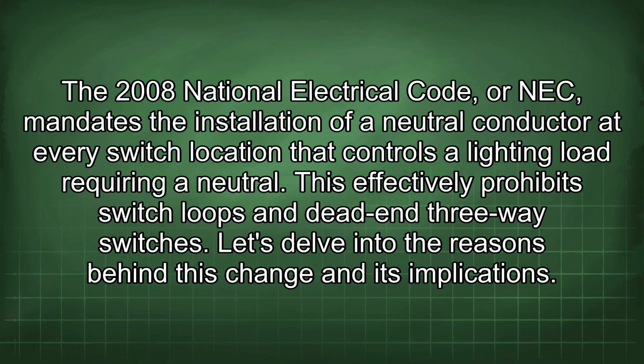The 2008 National Electrical Code, or NEC, mandates the installation of a neutral conductor at every switch location that controls a lighting load requiring a neutral. This effectively prohibits switch loops and dead-end three-way switches. Let's delve into the reasons behind this change and its implications.